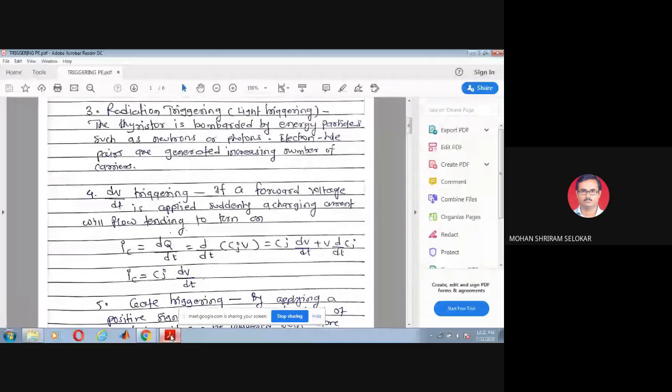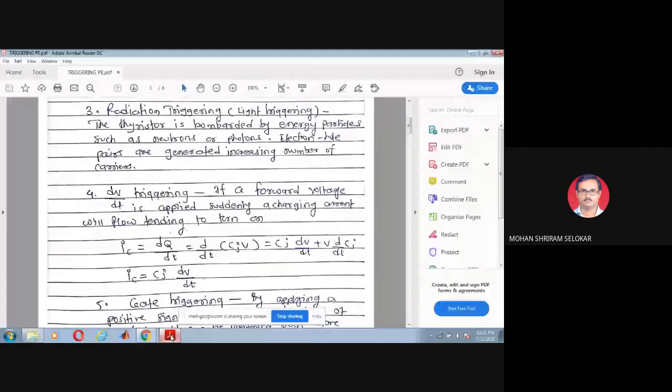In a capacitor, you can find that charges are collected at one plate, positive charges collected on one plate, and negative charges collected on the other plate. So basically, you can treat the junction J2 as a capacitor in which positive charge is collected on one side of the junction J2, and negative charge is collected on the other side of the junction.